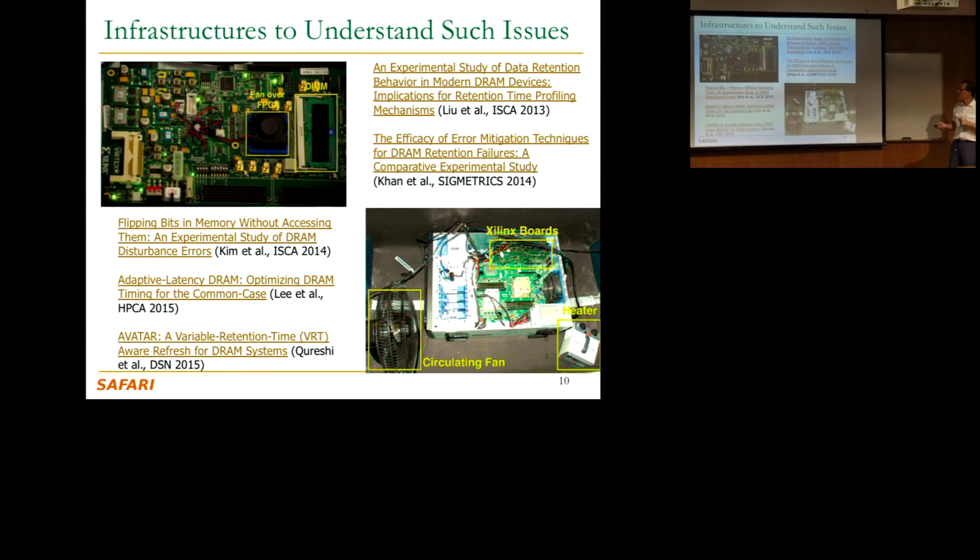And as I said, we also designed a bunch of low-level infrastructure, FPGA-based memory controllers. This is the first incarnation of that infrastructure to test these scaling issues with DRAM. At the time we started with the retention time issues. We wanted to understand the retention time of DRAM. And we also looked at latencies later. And I'm going to talk about RowHammer, which is something we discovered along the way.